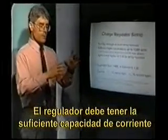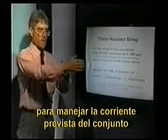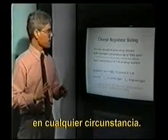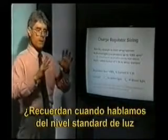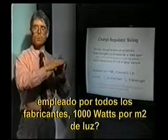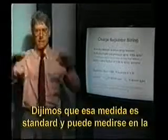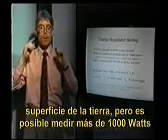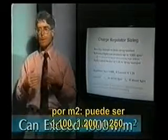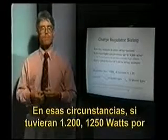We have to size the regulator large enough in terms of current capacity so it can handle the expected current from the array under all circumstances. Remember, when we talked about the standard light level that's used by all manufacturers, 1,000 watts per square meter of light, we said that that measure is standard and can be measured on the Earth's surface, but it is possible to measure more than 1,000 watts per square meter. 1,100, 1,200, 1,250 is not unusual.